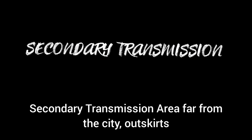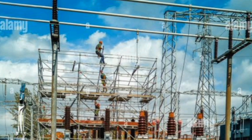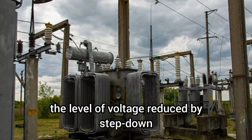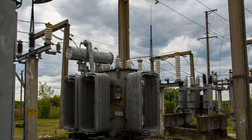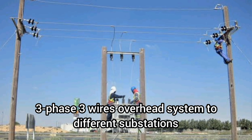Secondary transmission. The area far from the city, the outskirts, which is connected with receiving stations by lines, is called secondary transmission. At the receiving station, the level of voltage is reduced by step-down transformers to 132 kilovolts, 66 or 33 kilovolts, and electric power is transferred by a 3-phase 3-wire overhead system to different substations.